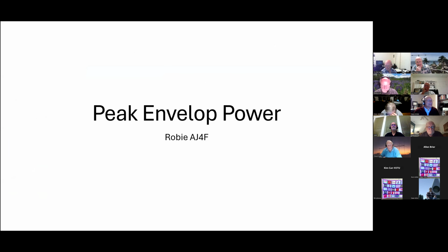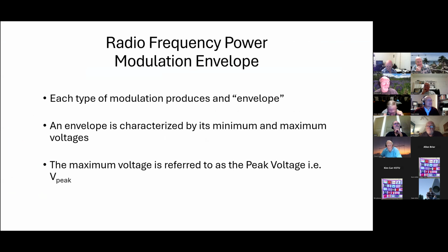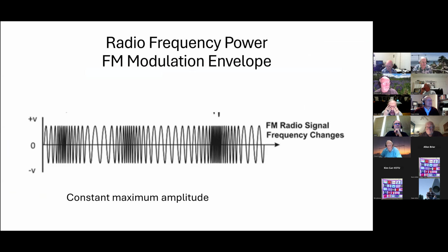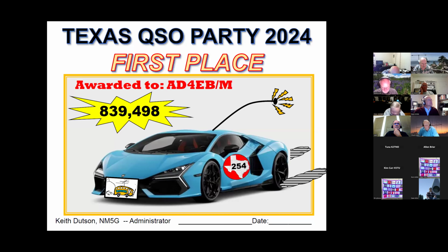Two things. You come across all these voltages you're throwing out here, which is a great thing, but you've got to worry about the coax you use, because a coax does have a tolerance and a peak breakdown voltage associated with it. So when you're looking at the overall system, that's one thing to look at. Have you looked at how you measure this stuff? What's a good power meter to measure this? Is it some MFJ device? Is it an LP100A? Is it the Alpha? Have you looked at any of that?